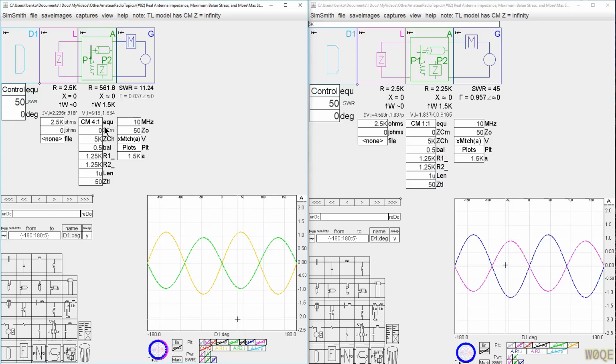If the antenna itself had some impedance, say 1 kiloohm, we'll see that this gets just a little bit better, but not appreciably. And 1 kiloohm is quite a bit of common mode impedance on the antenna. So we don't gain a lot there. Where we gain a lot in having common mode impedance in the antenna is if the choke is going to have a very low impedance. But 5 kiloohms is getting to be a lot of choking impedance, and we still see an imbalance. People don't mention that very often, and that's exactly what happens. Making that higher than 5 kiloohms is extremely difficult. The imbalances are just incredibly hard to control.